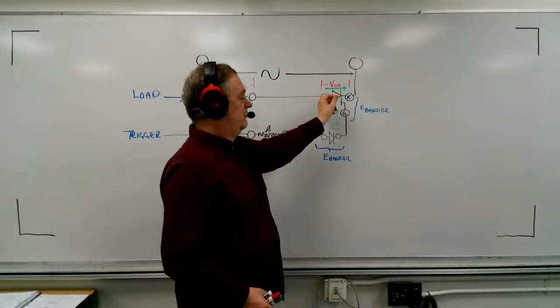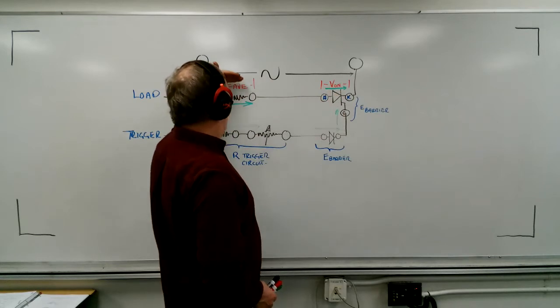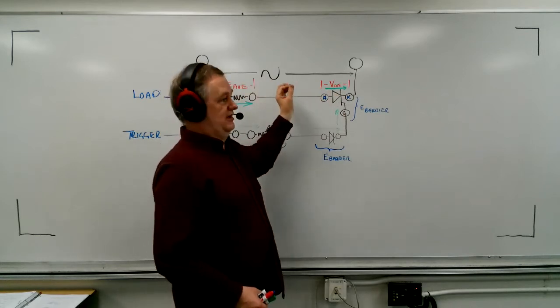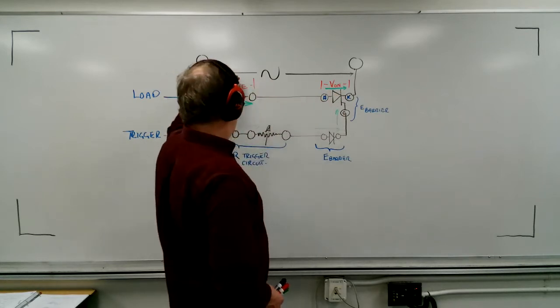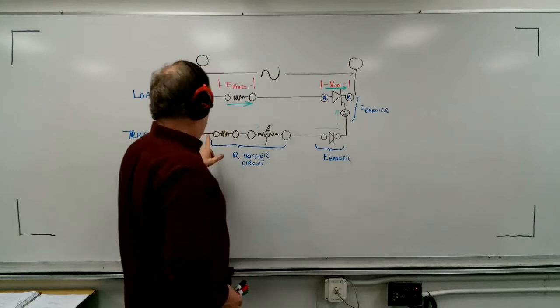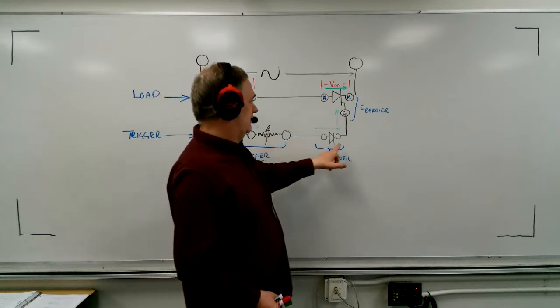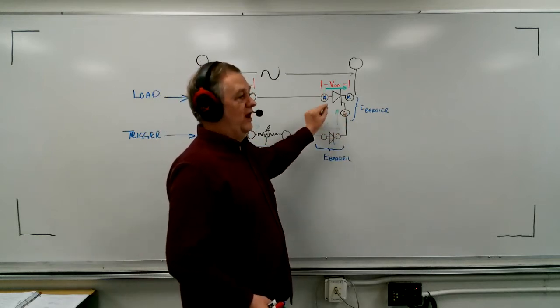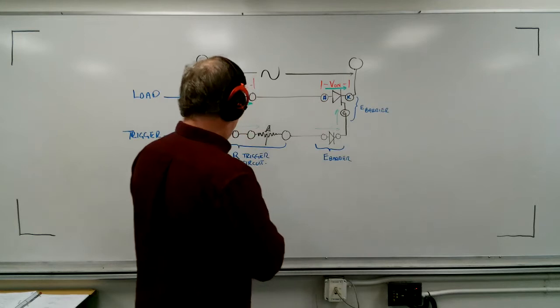Depending on when this fires is going to determine how much of the waveform is cut away, and that will in turn determine how much load voltage there is. And this is just the trigger circuit, and it, of course, is going to determine when the firing angle occurs. So